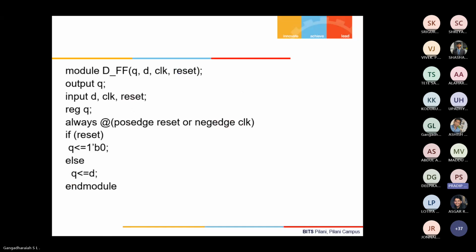So this synthesis, does it give us only the netlist schematic, or does it also give us the physical design? When we do the synthesis of this Verilog, it gives us the schematic design, right? Does it also give us the physical design of that module? When you synthesize this, does it give physical design? That's the question, right?